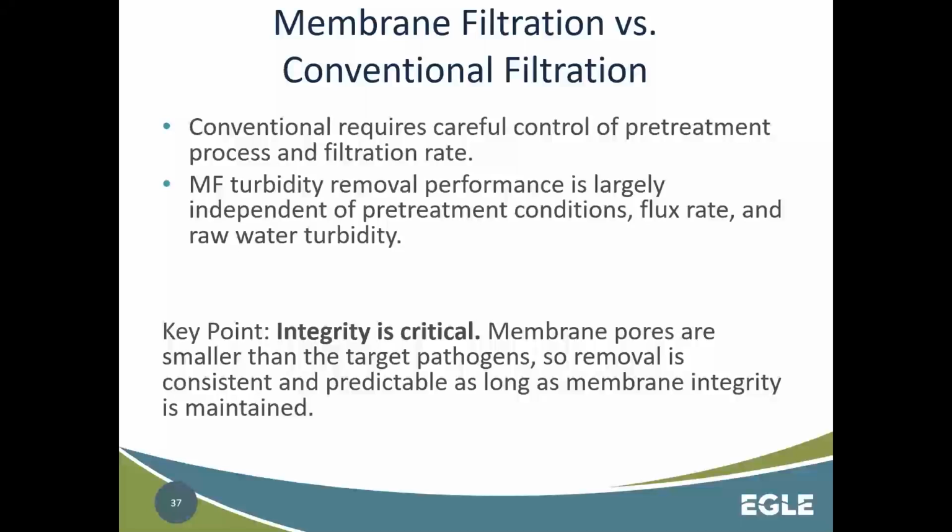So, as I said, the key point with membranes is integrity is critical. Those membrane pores are smaller than your target pathogens, so removal is consistent and predictable as long as you have the integrity.